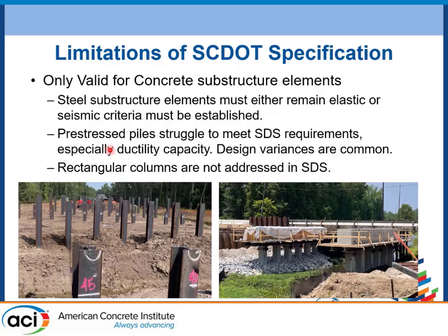Same thing for pre-stressed piles. That is covered in the SDS, but it's very challenging to meet the SDS's ductility requirements for that substructure type. So we often have worked with the DOT as well to discuss options for variances from those requirements for pre-stressed pile. And I mentioned those problems.